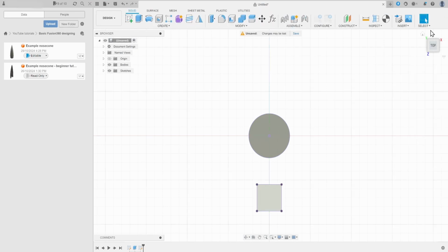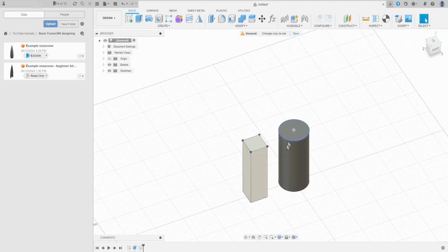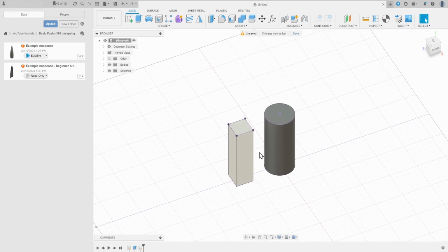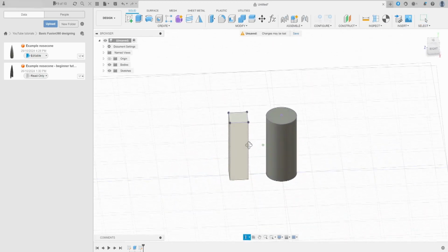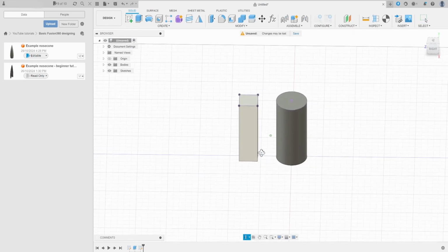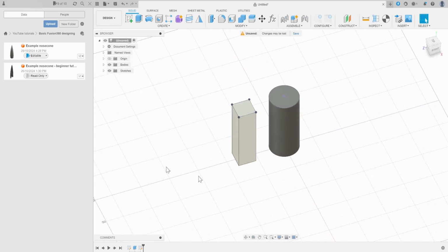Now, after that, for viewing, what we can do is we can hold middle click to pan and hold shift middle click so that we can orbit it around and also choose exactly where we want to center our viewpoint. Middle click is the scroll wheel when you push down on the scroll wheel. You do not roll the scroll wheel. The use of appearance is to make your model look prettier or to color code parts.